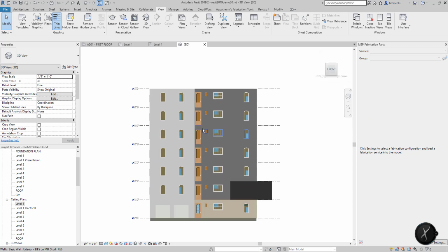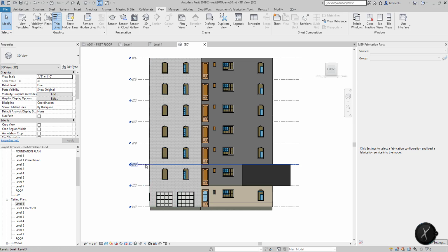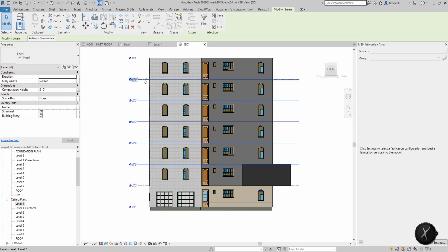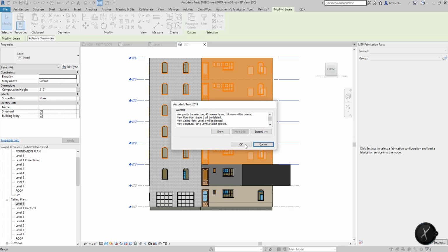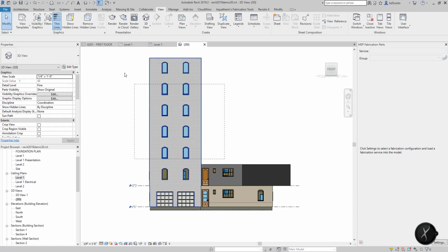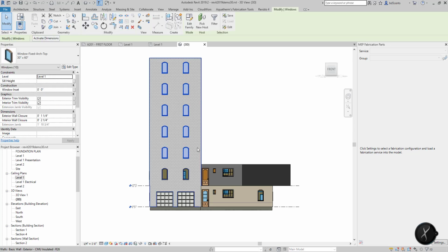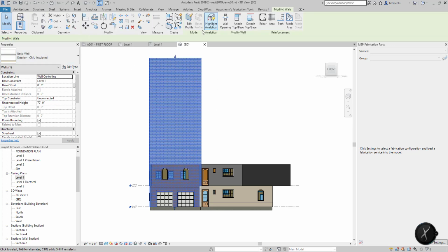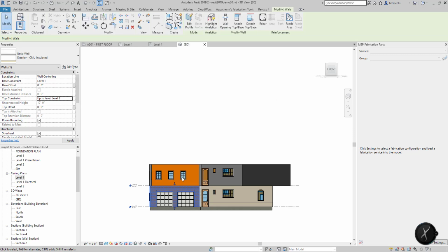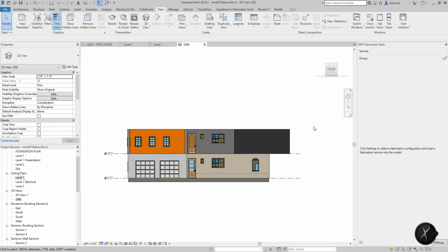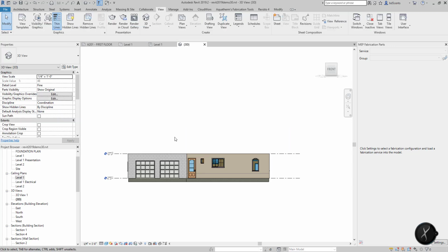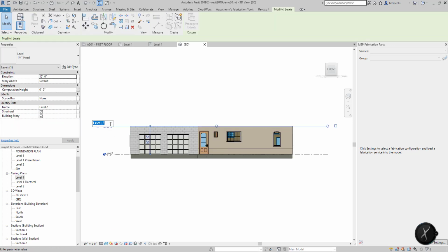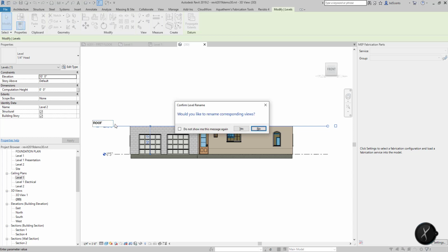and we're going to eliminate floors 3, 4, 5, 6, 7, and roof. We're going to delete those, and all those values will be gone. We'll do another window selection and delete those, and then we'll set these walls, which you can tell are selected, up to level 2 for now. We'll delete those instances of those windows as well. We're going to continue to delete things on the second level there, and we're going to rename this to roof. So we'll just call this roof.